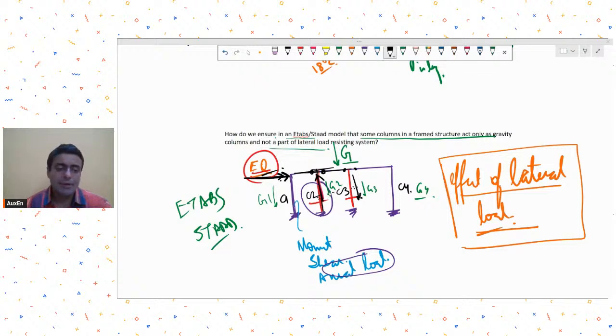So now this is a big implementation problem, and we really don't know what to do in such cases because the code does not tell you a proper process. Most of what is done from here onwards is pure jugaad adopted by practicing engineers. So what will be one of the jugaad? One of the jugaad can be to give a very, very small axial modifier.